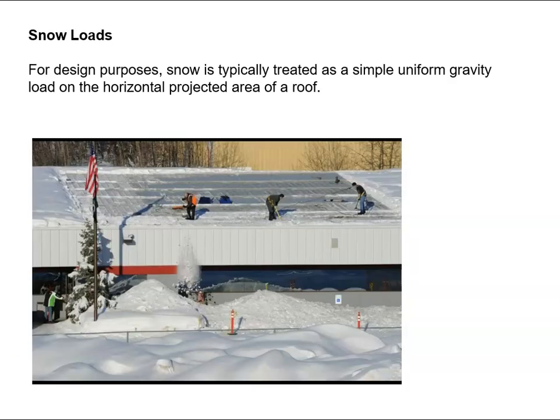All right, and then finally just snow loads, very simple. For design purposes, snow is typically treated as a simple uniform gravity load on a horizontal surface. So it's typically pretty straightforward. It has caused some serious problems though, so it is potentially dangerous, but relatively straightforward in its calculations.